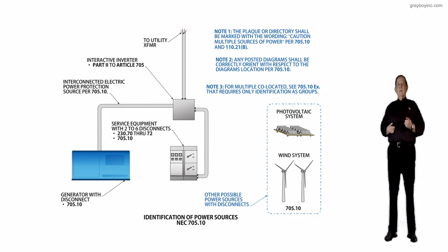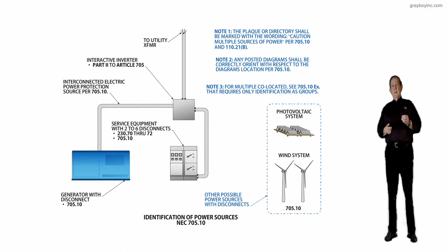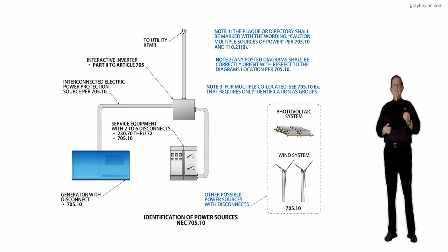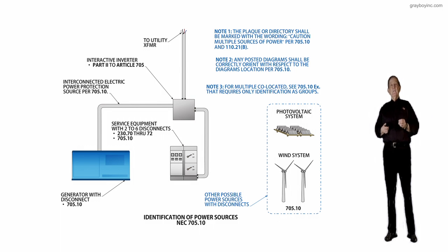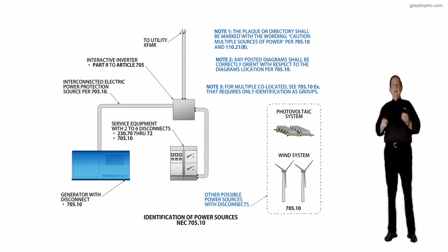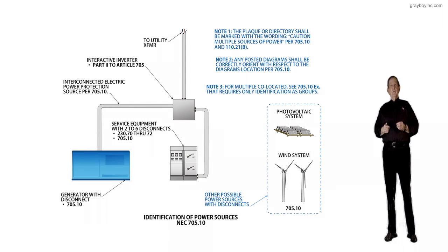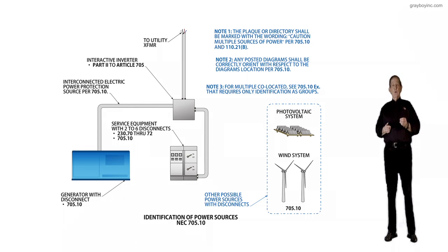And then we said the transfer switch can be a 3-pole or 4-pole in compliance with 250.30 informational notes 1 or 2. If the generator is installed permanently, then we said see 250.35(B). Load and supply, we identify whether it's load or supply, and 250.130 and 250.142.